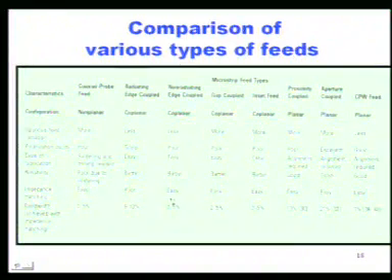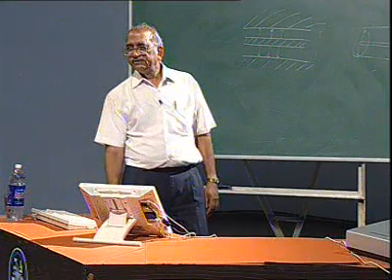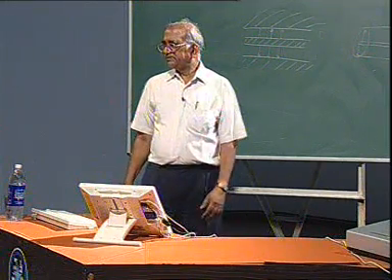Impedance matching, radiating edge coupled feed. The impedance matching is a problem because the input impedance at the radiating edge is very high. Okay, either you introduce an impedance transformer or you can introduce a gap.